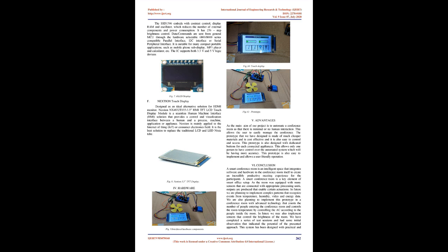One of the best things about these relays is that the two optocouplers present in it provide good isolation between relay and Arduino. We have 3 channels per relay broken out to blue screw pin terminals. The channels are labeled for their function: common (COM), normally closed (NC), and normally open (NO). The names explain the state of the channel with relation to the switch at rest.